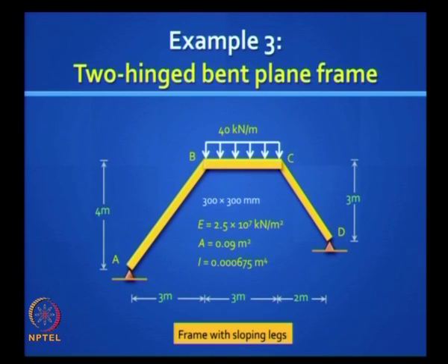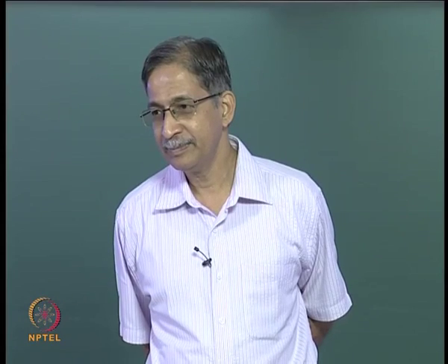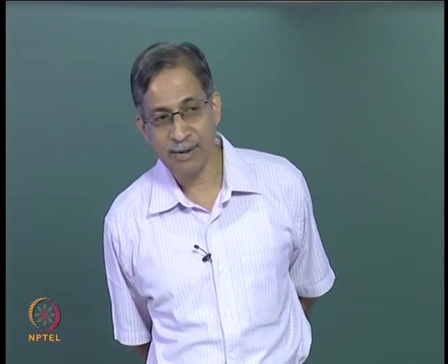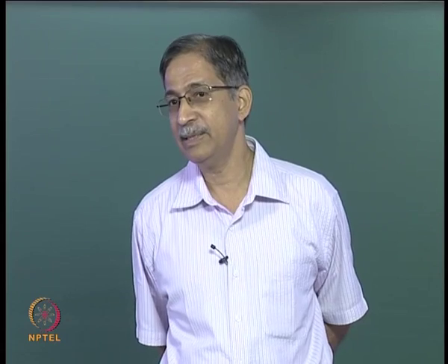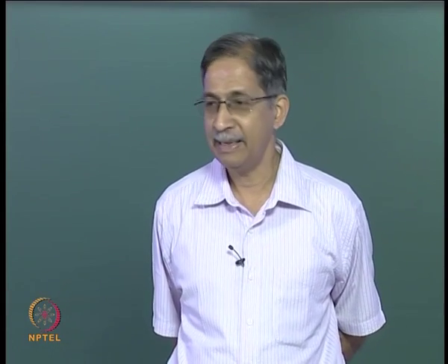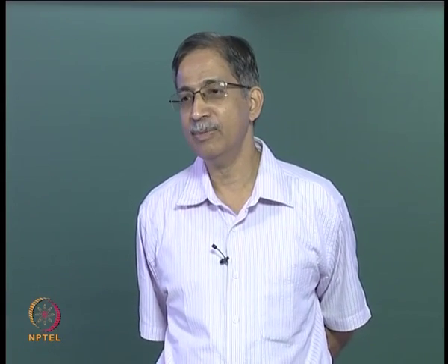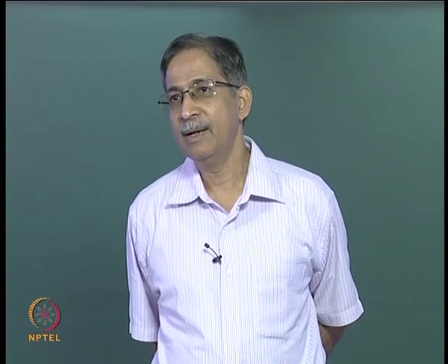Why do you get different answers? Yeah, because here we are doing it more accurately. We are including axial deformations, which we did not have earlier in the slope deflection and moment distribution method. So how do we deal with this problem?